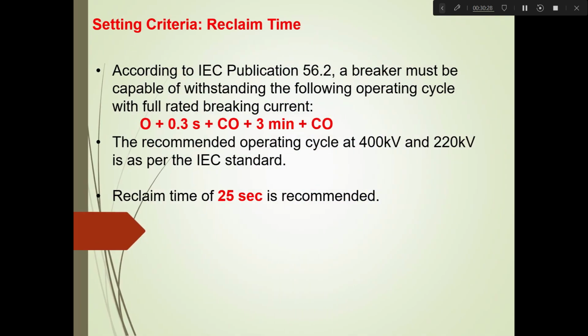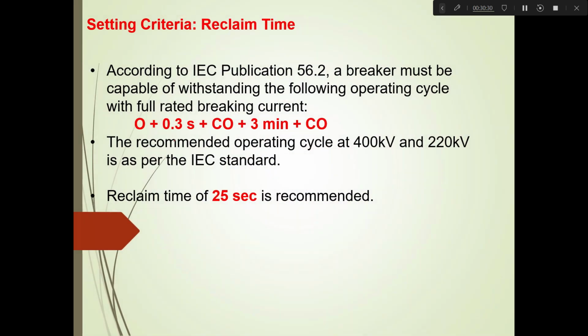So now we will discuss about this. As per this IEC publication, all breakers should follow this duty cycle. The meaning of this duty cycle is that all breakers should always be ready for one open operation or one trip operation. Once it opens or trips, then after a minimum time of 300 millisecond only we can close the circuit breaker, but generally in power grid we are using 1 second, so this is not a problem. So only after this 300 millisecond, or in power grid 1 second, we can close the breaker.